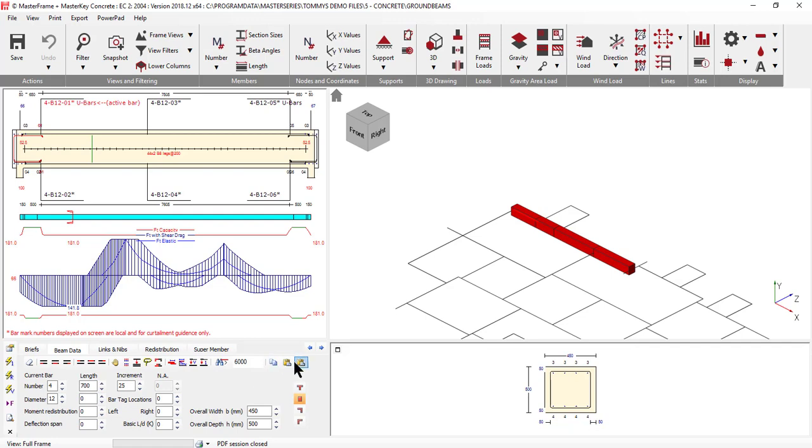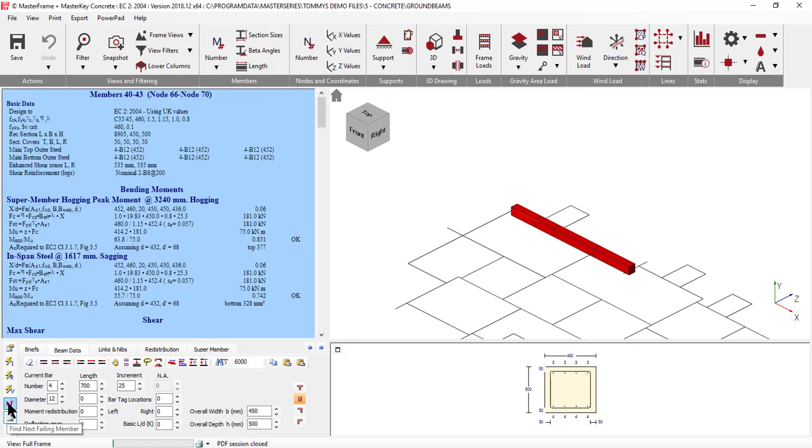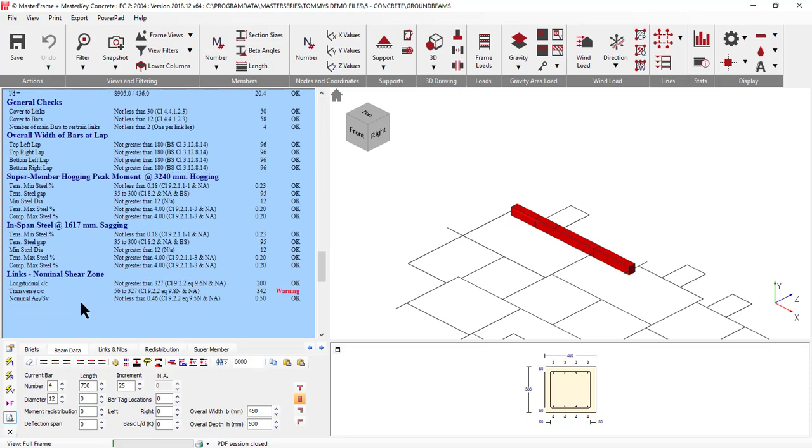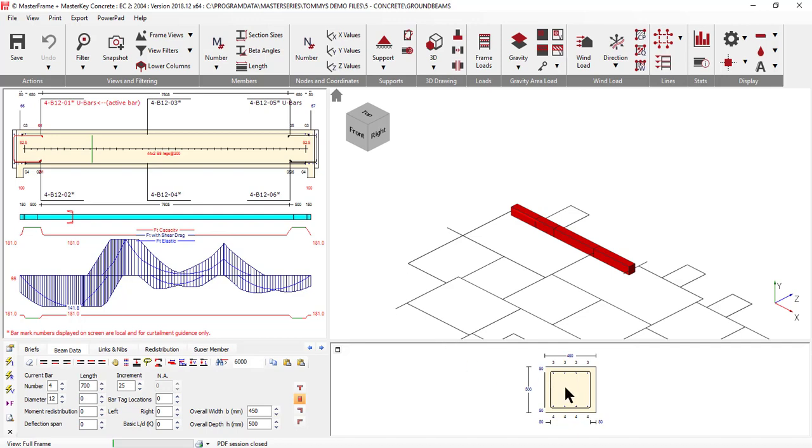Now, having designed all your beams, you can have little options like let's go and check and scan for failure. So run along and it stops at the first failure it finds, and it is to do with the transverse reinforcement cross centers, and it's just saying that we're too far apart in some of these rebars, and we just need to sort that out. So the transverse center of the links is too far, and we need to put another set of links in to sort that out. But it's very small, it's within 25 mil, so I would actually argue that it would be okay in this case and just get on with it.